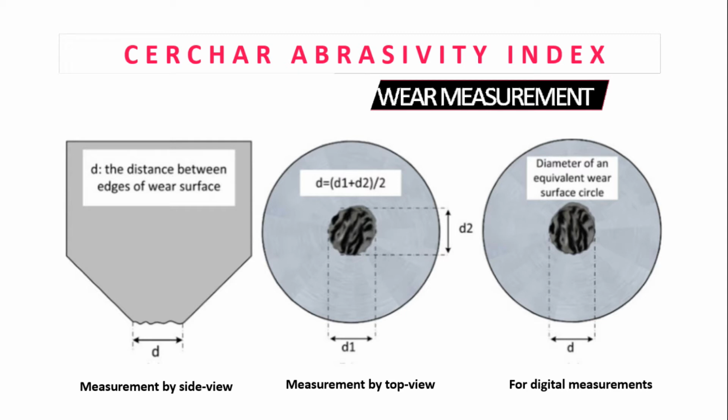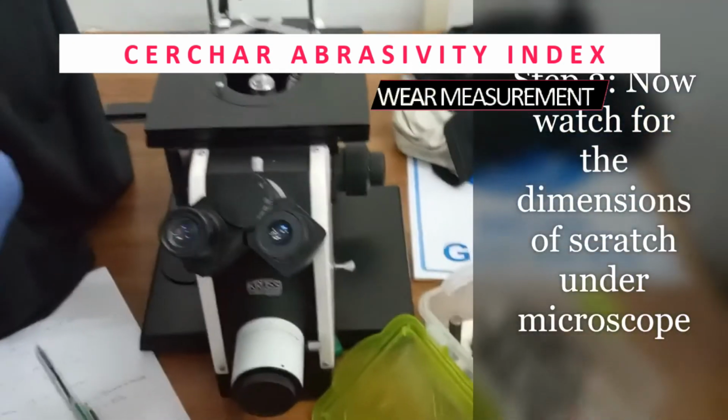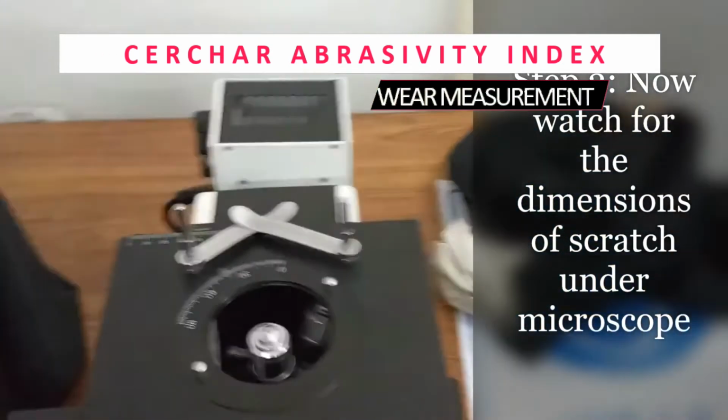When testing a fresh fractured rock surface, especially in harder rock types, the wear flat can often exhibit a non-symmetrical shape with splinters or burrs of steel that stretch beyond the wear flat. These can affect measurements by making it difficult to determine the true diameter of the wear flat by top view measurements. A correct determination of the start and end points of the wear flat, as stated by Rostami et al. in 2005, is crucial to the accuracy of the test, which might otherwise contribute to large variations between different operators and laboratories.